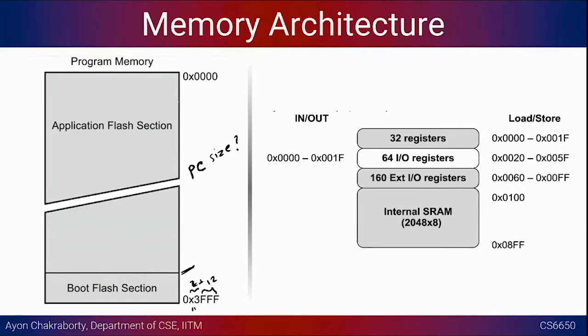And then apart from this, we also have these registers. We mentioned these general purpose registers, these 32 registers, that are within the CPU. And then there is this input output registers. As I mentioned, you can interface various sorts of peripherals and configure those peripherals here. It could mean different things, and those details are given in the instruction manual, and I'm going to show you some examples. And then there is this free space that you can use for your programs.